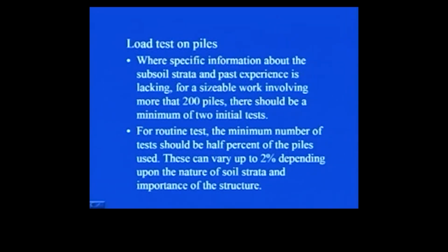For routine tests, the minimum number of tests should be 0.5% of the piles used. That is, let us say you are using 100 piles, so half a percent of 100 piles, that many tests you must conduct on the working piles as far as routine tests are concerned.